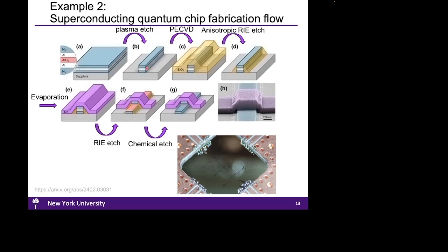Next, through a combination of lithography and etch, this material stack is shaped into a rectangular pattern. The next step forms SiO2 spacer regions, a process similar to what is used in fabricating transistors. To form the spacer regions, the SiO2 is first deposited through plasma-enhanced chemical vapor deposition onto the substrate, and then through an isotropic reactive ion etch, the spacer regions are formed.